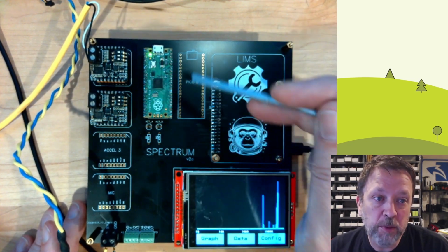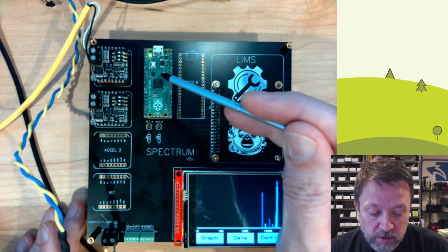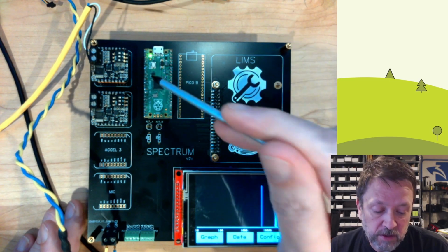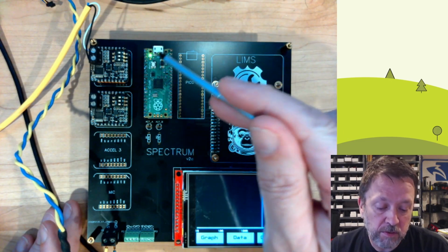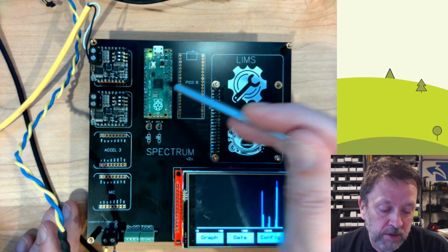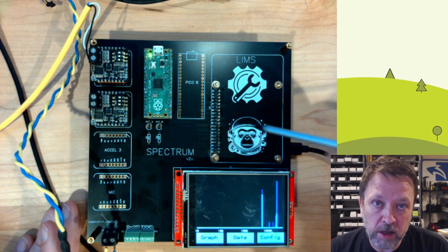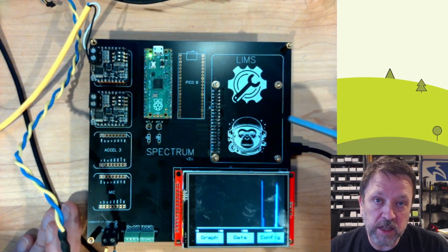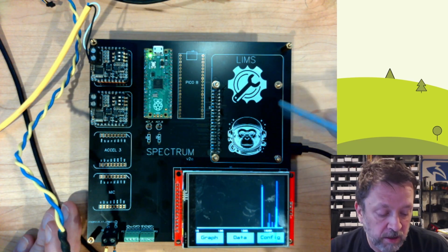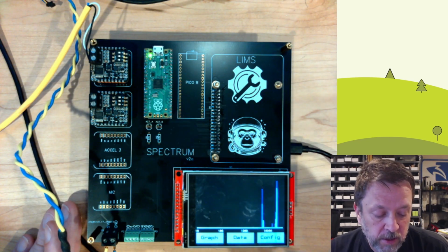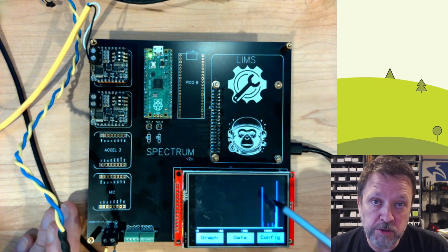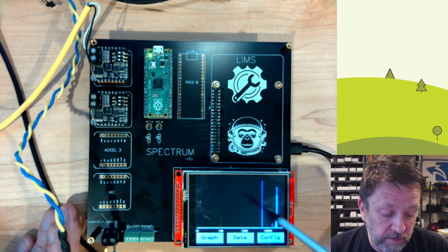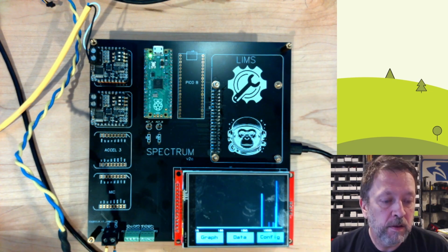The real-time capability of this solution is written in C over here, but I would not want to try to do this rendering in C. So we transition from the real-time C stuff, transfer that data to the processor that is running .NET, and then over in .NET, I'm able to use all of the convenience and speed of development there in order to generate the application that allows me to provide user display on this HMI, as well as exfiltration of the data through something like a WebSocket. So that's it for today.